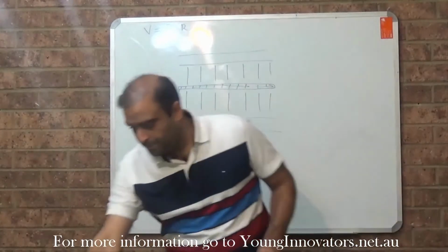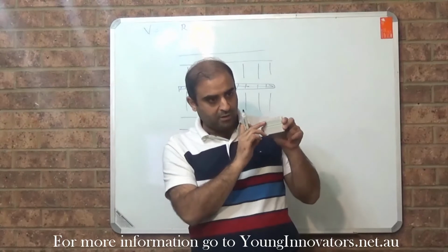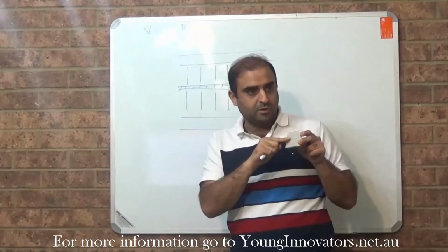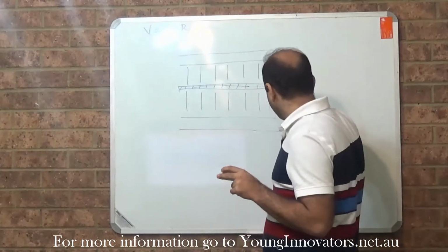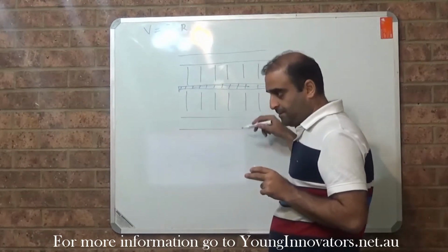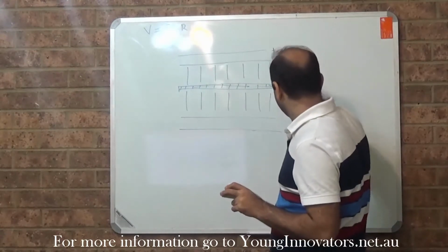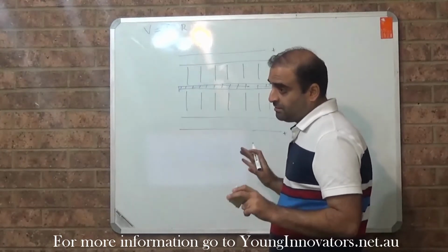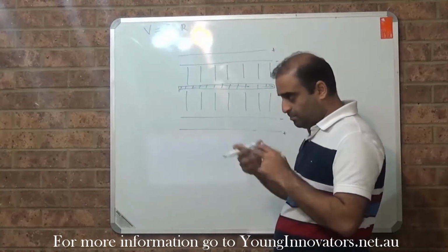This red line is all connected, right? This blue line is all connected, right? These ones here are not connected horizontally, they are connected vertically. And then you can see this little gap in the middle. This gap breaks the connection, and the bottom ones are also connected vertically, right? This red one is the plus sign, and this one is the minus sign. So you remember plus and minus? These are plus and minuses, and these other ones are to connect things together.